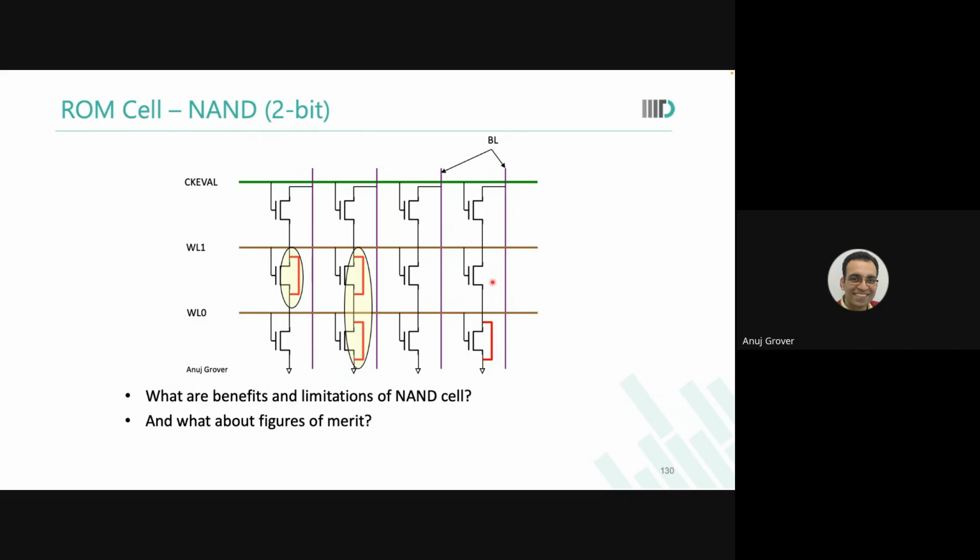Look at the other cell. There is RCK. There is RM1. And then it goes to ground. Are you able to see this? So you had some particular voltage over here. Do you realize now the current that the 2 bit lines will sink is going to be different? That is a source of variation for you, a systemic source of variation for you. Which means that you have to margin for all the possible combinations that there could be.